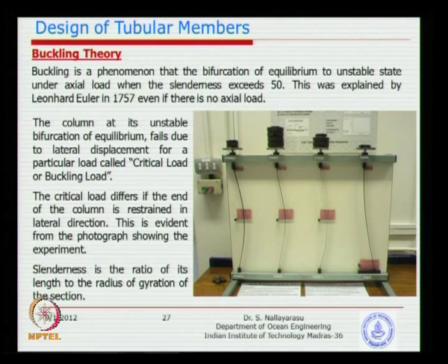So, you might have studied buckling theory in your applied mechanics, most of you might have learned. The support systems govern the carrying capacity of columns. Basically Euler theory is one such for global buckling. You can see this experiment they have done with different boundary conditions, they carry different loads for a simple column.